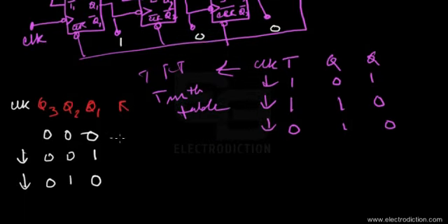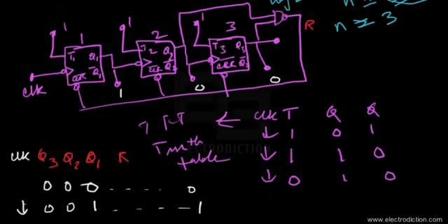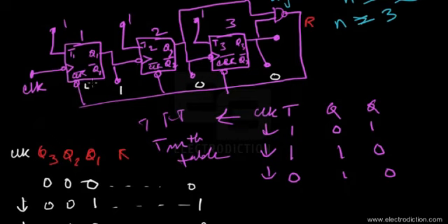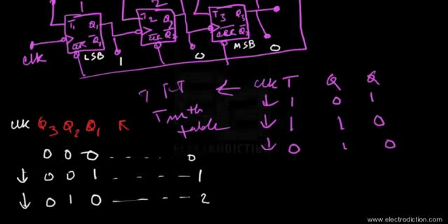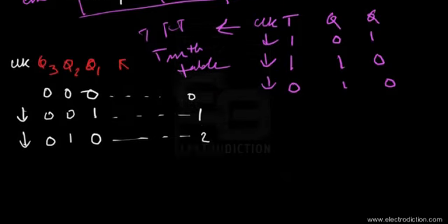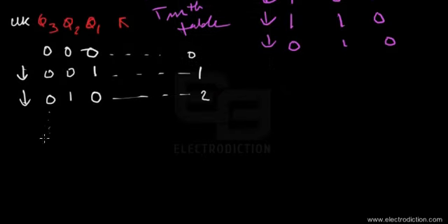If you take a look over here, this represents the 0th state. This is the first state, that's state number 2, that's the second state, and the count moves on this way. Here flip-flop 1 represents the LSB of the binary digits being generated as the count of this circuit, and flip-flop 3 represents the MSB. The count moves through all these states, and slowly it goes to stage 5, where we would get an output of 101.